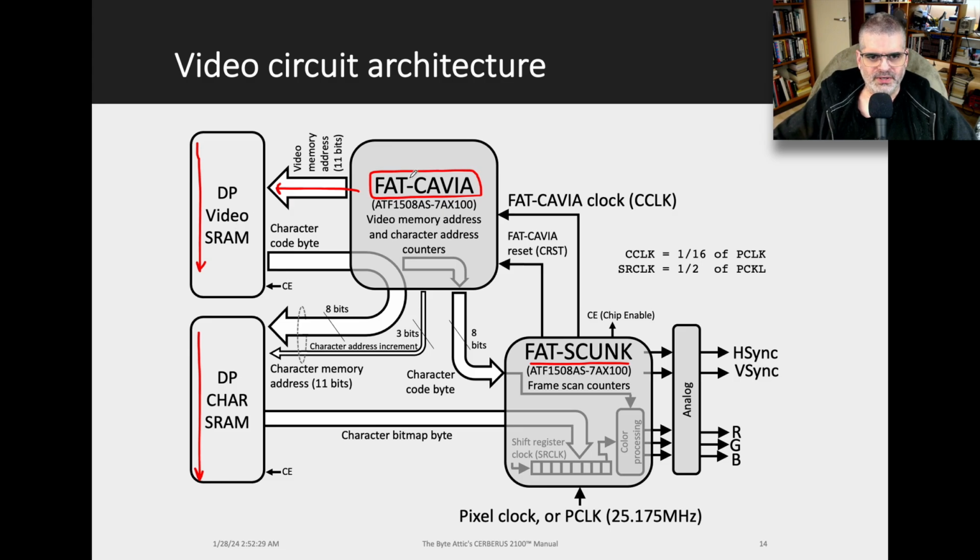Remember, it has to come back to the same row of characters 16 times to double sample it and print all the bytes of the character bitmap, and then it goes to the next row. So there are a lot of counters here to keep track, to manage the proper jumps, the proper counting.